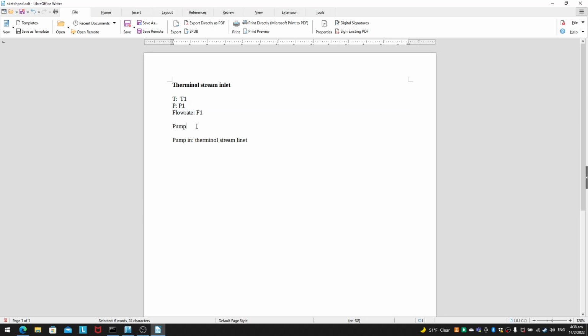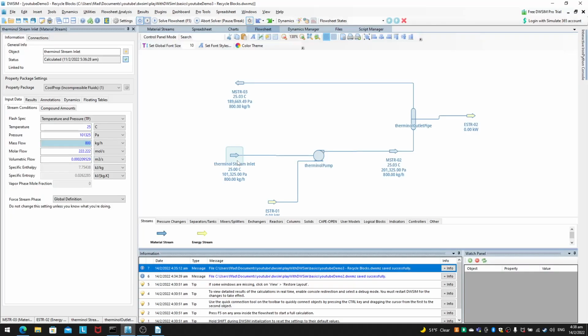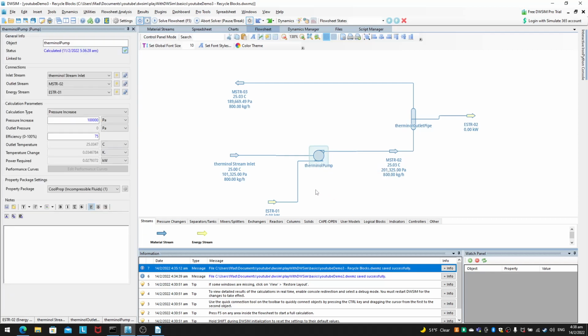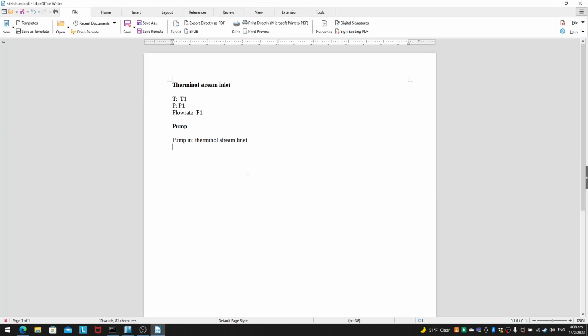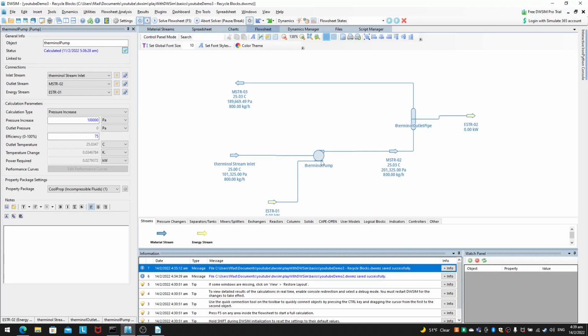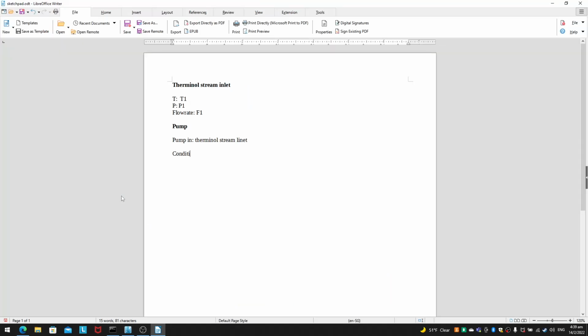And the pump, you don't simulate the full pump. In the context of DWSim, of course it looks like a pump here, the diagram looks like a pump. But what's going on behind this pump is just an equation. So for example, over here we dictated that pressure must increase. Our condition is pressure increases by 100,000 pascals. So the pump in the sense of the code